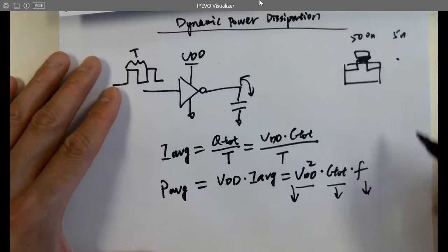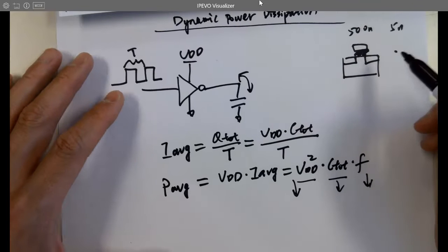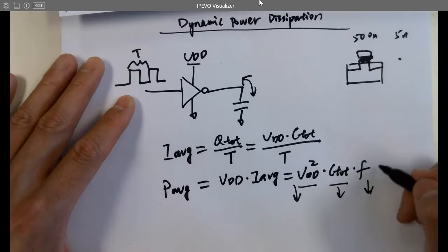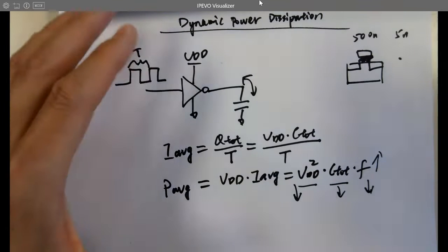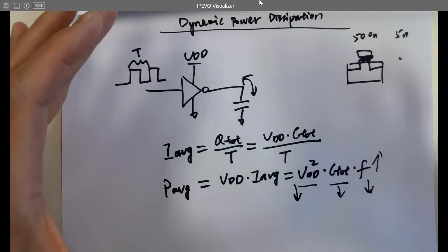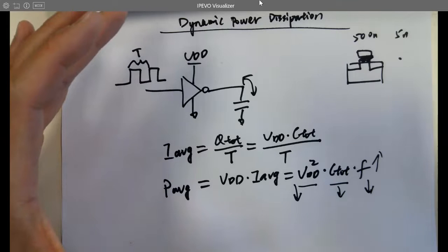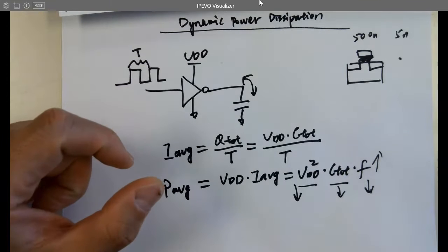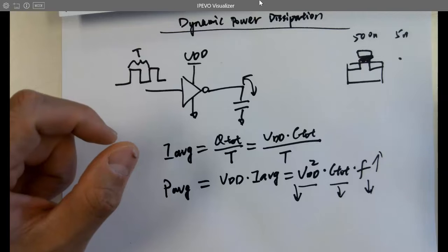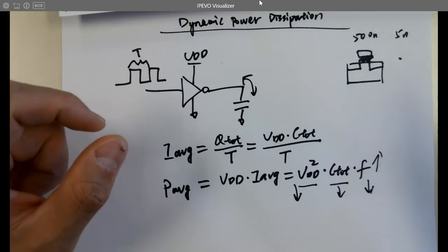And power. Whenever you get smaller transistors, you can run them faster. Like with 5 nanometer technology, we can usually run it a lot faster than the 180. So it's going to increase the power consumption. That's why, when you integrate more circuits in the same footprint on the silicon die, you can definitely run it faster because these are smaller transistors. So that's why it introduces a lot of heating problems for the chip. It's the same area, but more circuits and a faster clock.